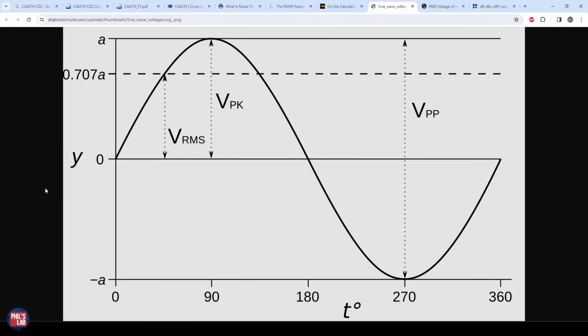What we'll be seeing a lot is, for example, RMS quantities, maybe peak, peak to peak, and so on. So it's important to understand what these mean. Effectively, when we're looking at sinusoidal type signals or AC signals, rather than taking an average, we typically look at an RMS, a root mean squared average, so to speak. If we take, for example, an average of this sinusoidal signal, that'll simply be 0 because we have equal areas above 0 and below 0, so effectively those areas cancel out. So we need a different method to calculate an average, and that's root mean squared.